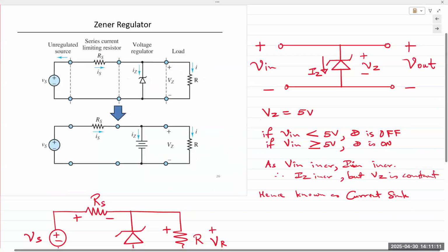Okay, so quick and brief recap. All right, so we introduced Zener diodes. Zener diodes have the property of being operated in the reverse bias. They hold the voltage across their terminals constant. This property allows us to use it as a voltage regulator. Voltage regulation means keeping the output voltage constant regardless of what changes in the circuit. Those changes could be series resistances, load resistances, and also supply voltages.